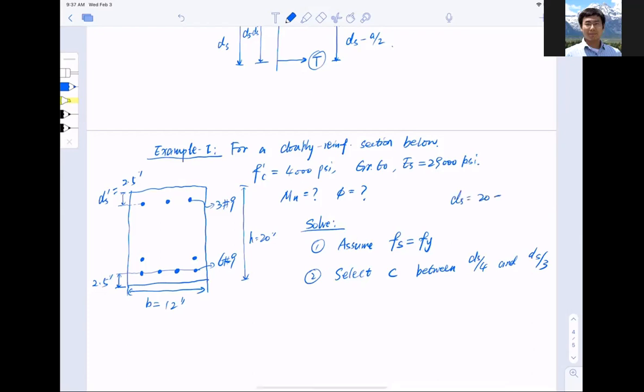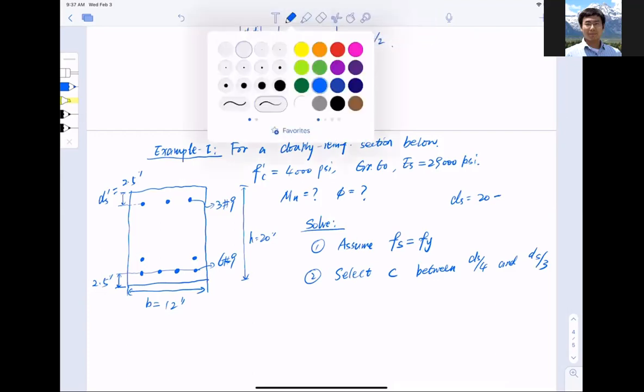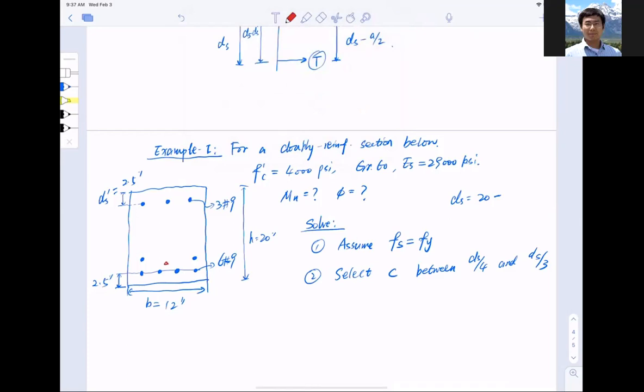Now I'm going to make some approximations. I know that I have 2 rows, and a distance between the first row and the second row, but to make it easy on us, I'm just going to use a known depth. I would say ds is given as 16.8 inches.